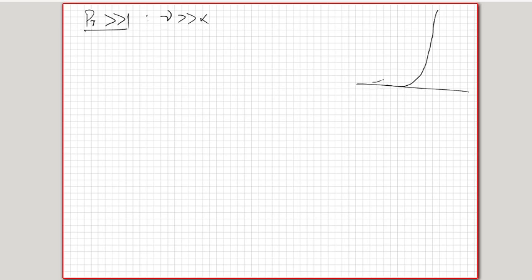Okay, and the momentum boundary layer is very thick. So if I look at the thermal boundary layer, delta T is much less than delta. Okay, so this is your delta T, and delta will be somewhere here. So what happens is that in the bulk of the thermal boundary layer, the eta is extremely small. Okay, so if I look at the eta coordinate, the eta is very small in the thermal boundary layer.